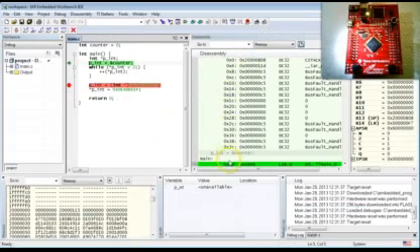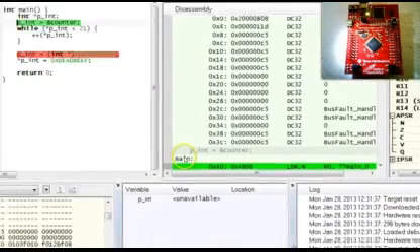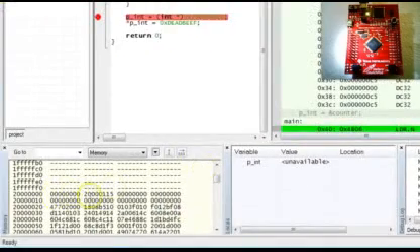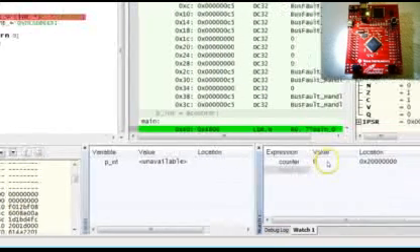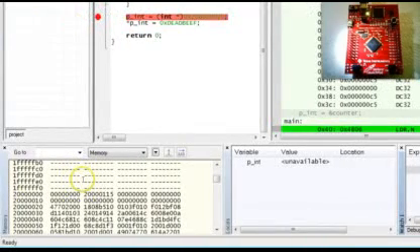First, at the low addresses starting with 0, you can see the machine instructions. This is the compiled code of your program, which is stored permanently inside the microcontroller. This means that the low addresses starting from 0 are mapped to the flash memory. You also already know that the addresses starting from hex 2 are used for variables, such as the counter variable. That means that the address hex 2 followed by all zeros marks the start of the random access memory, RAM.